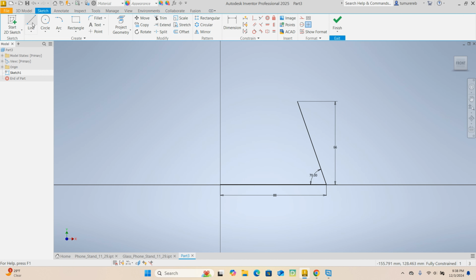Now let's go back to line command, and we're gonna try to align it here. So I'm gonna start my line at y coordinate equals maybe 30. Start from there, and then horizontal line. Again, perfect horizontal line. Don't do something like this, or that. Make sure it is horizontal. 0 degrees. Okay, 20.